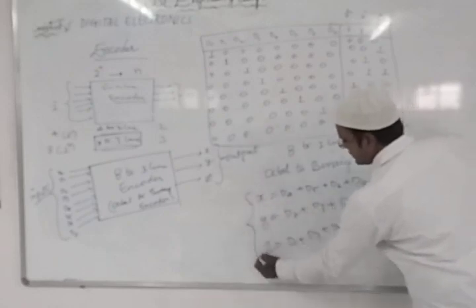Similarly, for the next combination, as you can see, it is D3. For the next combination, it is D5. For the next combination, it is D7. That means this is your output encoding, right? This combination of that particular thing produces this particular output X, Y and Z. So clear? This we can implement by using OR gate. For X, Y, Z, we will take those particular input combinations, D1 to D7. These are inputs, right?